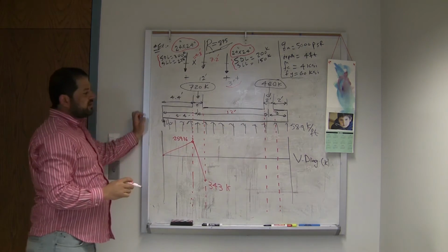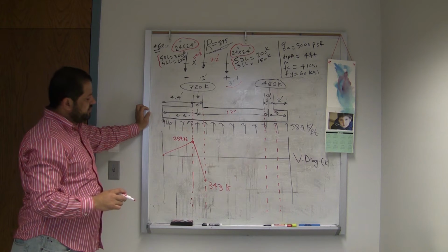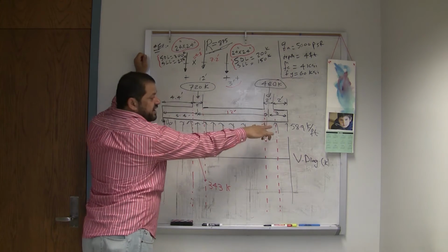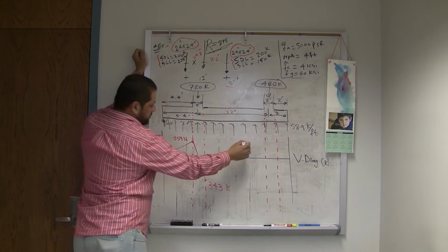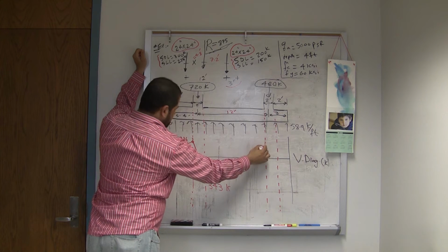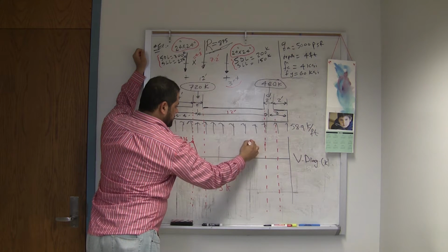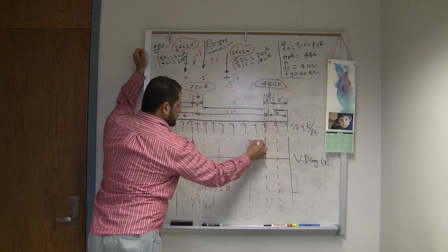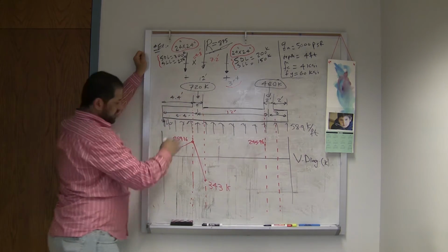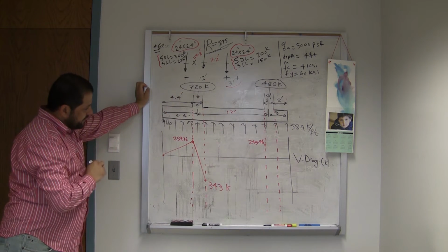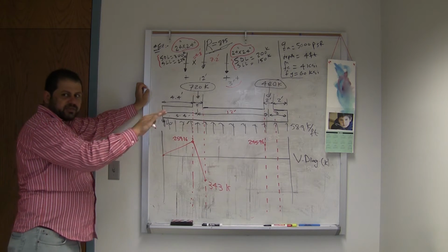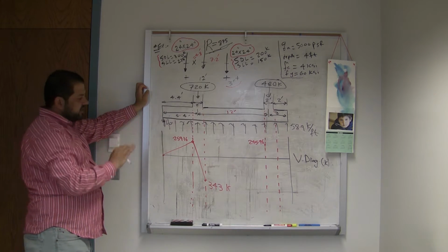That's 245.96, the difference. So you will get 589 minus that, which is 245.96, which again we're going to calculate at the end. Usually at the end, you will see the moment diagram is off by 5 kip-foot, which is not a big deal.